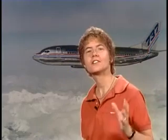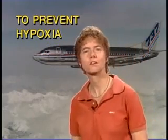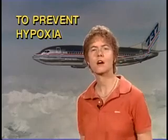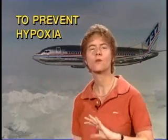Talk about cabin atmosphere control systems, and let's start with pressurization. Now, the whole purpose, the whole idea of pressurizing an aircraft is to allow operation at high altitudes and create an environment to prevent hypoxia. Hypoxia, of course, is lack of sufficient oxygen reaching the brain, commonly caused by flying at too high an altitude without oxygen or without pressurization, because what pressurization does is allow you to fly at the high altitude without worrying